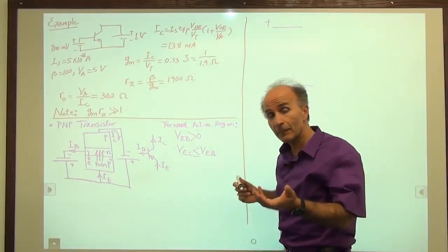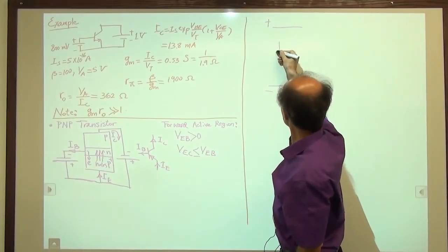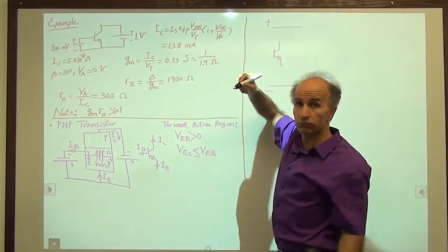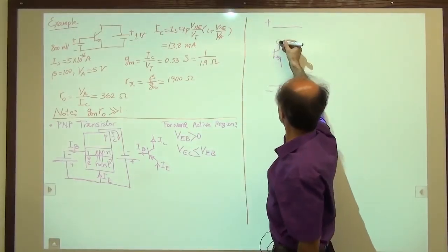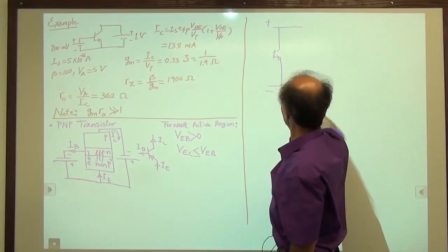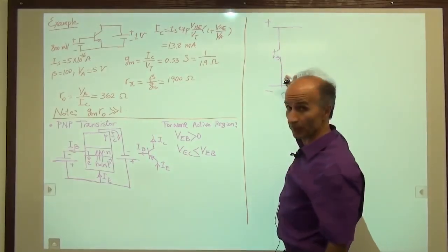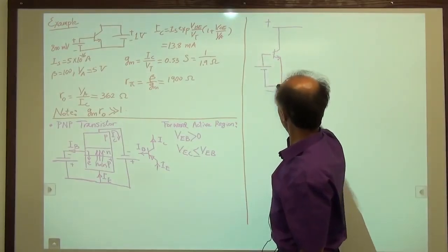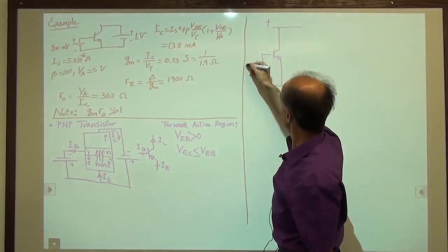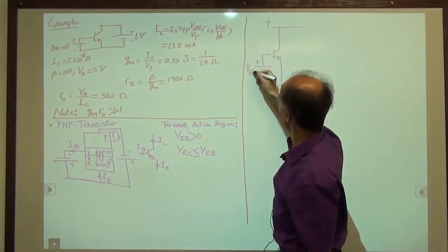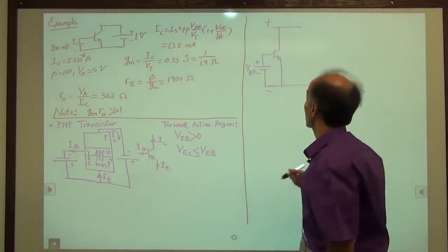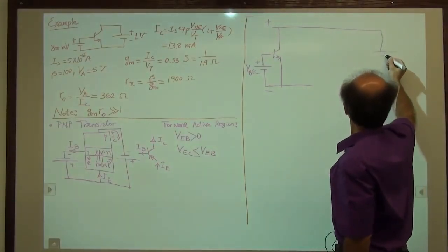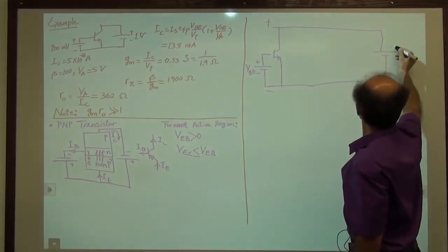Now if we have an NPN transistor, and we want to connect it to some voltage. Maybe we connect it like this, right? This goes up here, this goes down here. Collector is higher than the emitter. And then maybe we have another voltage for the base, so that is VBE. As we saw before, no problem there. You can imagine that this comes from a battery here. So place the battery over here, and we're good.